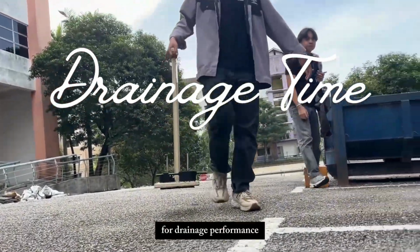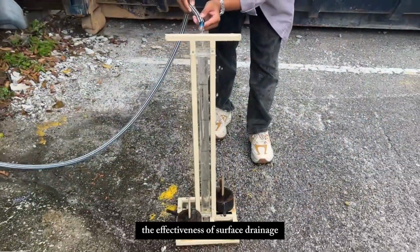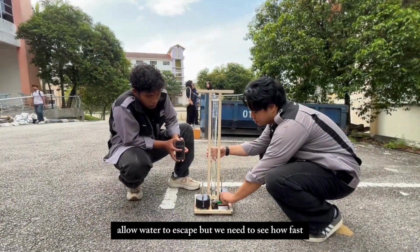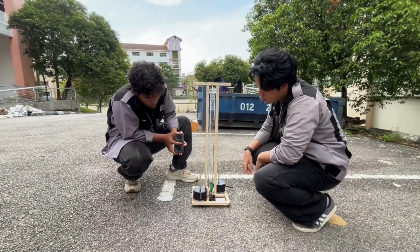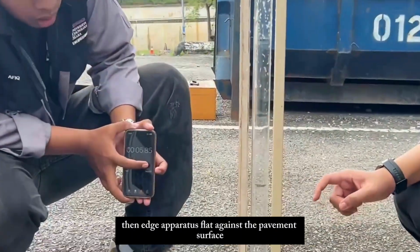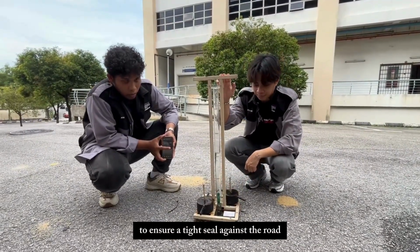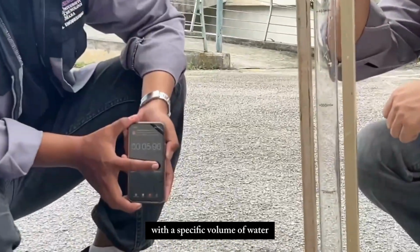For drainage performance, our final assessment evaluates the effectiveness of surface drainage. Good texture depth should theoretically allow water to escape, but we need to see how fast the water actually drains away. We place a specialized cylinder drainage apparatus flat against the pavement surface. Weights are added to the base to ensure a tight seal against the road. We then fill the cylinder with a specific volume of water.